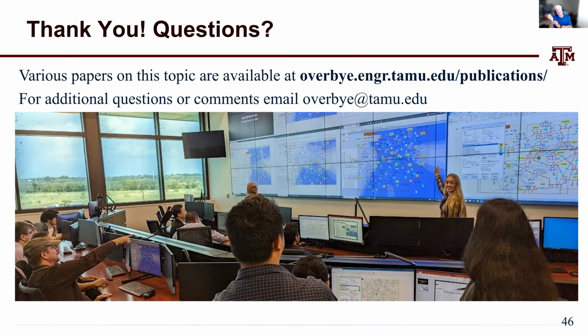But again, I just bring that up not because I think we should be looking at the stability of these values. If I had to say which solution I want, it's the solution that passes the dV/dQ sensitivity test. That's how I would check for it. But if you read papers on this, you will see people referring to these as UEPs. So I just brought that up so that people are aware that it's being done. But having said that, the power flow in and of itself does not have dynamics associated with it.